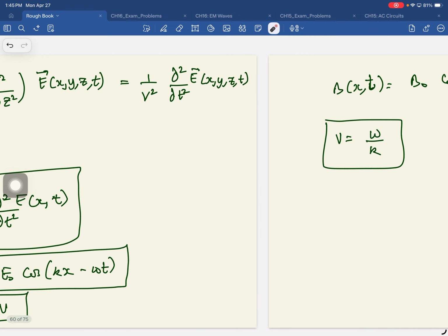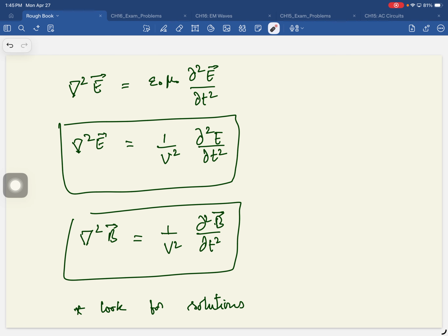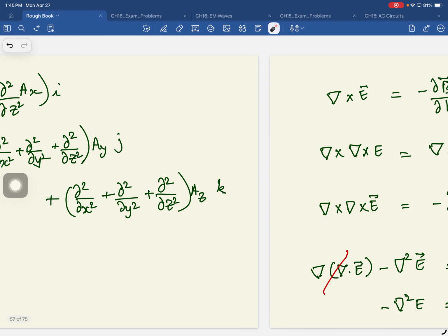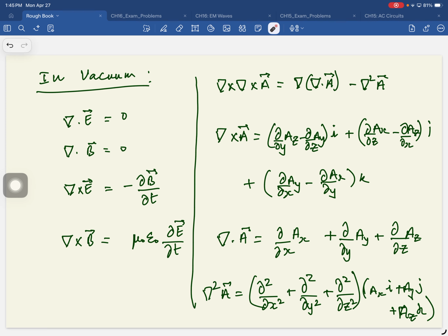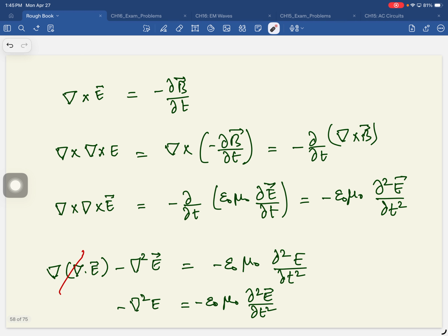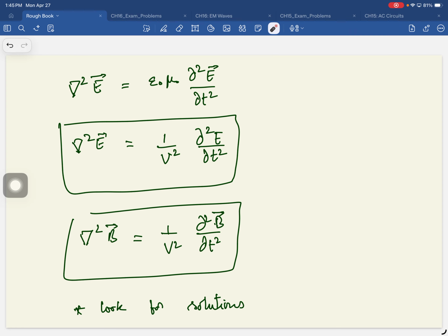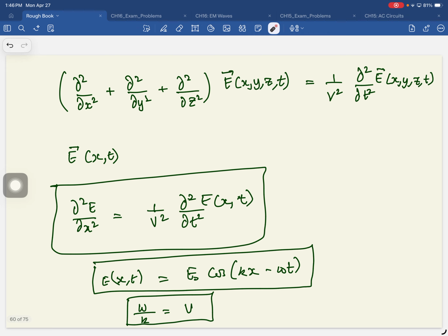Okay, so here's an RLC circuit. You know that the LC circuit oscillates, and the resistance converts energy into heat. So this AC source is pumping energy into the circuit, and if its frequency matches the frequency of the circuit, it can set up large amplitude currents, and then you couple this inductor to that inductor via a transformer.